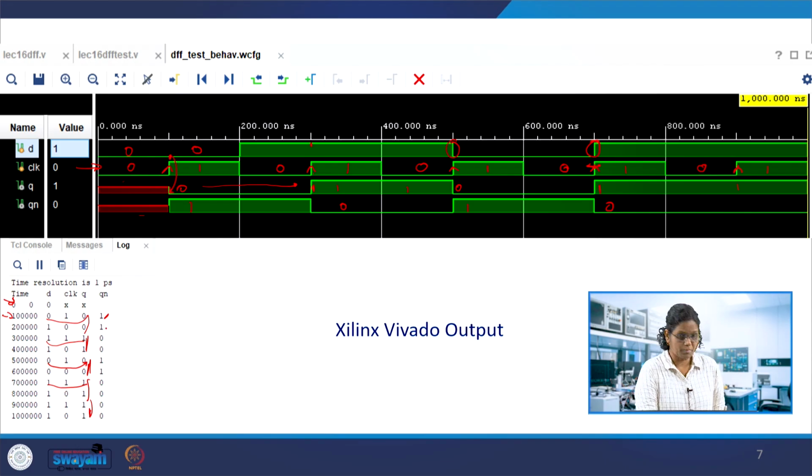So this is just a print of the values of the variables we have in the program. This is a simple D flip-flop without any reset or preset, and in this case it is positive edge triggered. If you want negative edge triggering, you can change posedge of the clock to negedge of the clock and do the operation similarly.